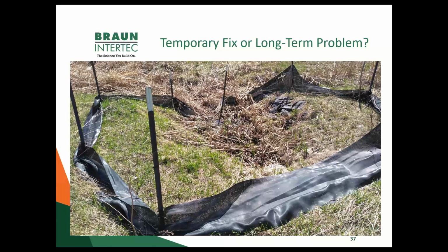Again, look at what is a short-term temporary fix, and whether it will create a long-term problem. What's your time window that you plan on being in that facility? If you're only going to be there a couple months, then yeah, a silt curtain at your outlet makes sense. If you're going to be there 10, 15, 20 years, maybe you want something a little more robust.